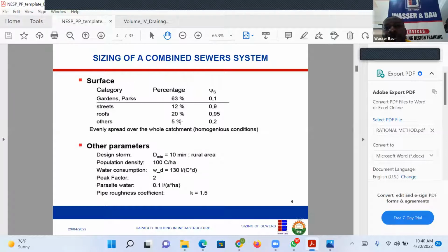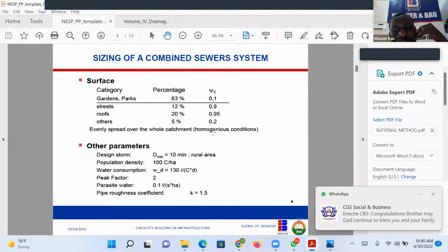So this is now, out of the 100% of the catchment, the characteristics of each of the sub-catchments. Now you get the average of this. If you get the simple average of this, you get it wrong. What we'll get is what we call the mean weighted average. There's a difference between mean weighted average and average, but I won't like to dwell much on it.